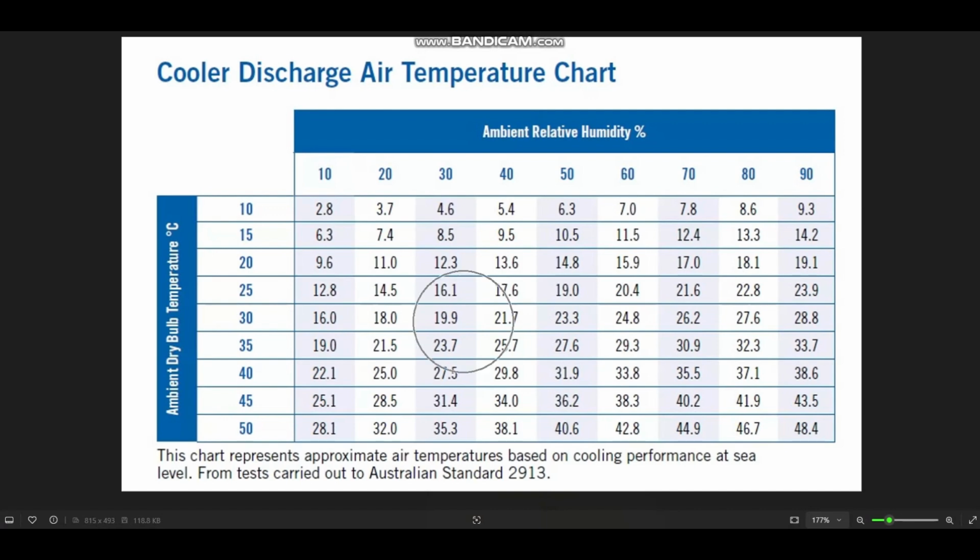So quick summary, 20 degrees at the bottom of your cooler, another 2 degrees through the flexible ducted network and all the twists and turns and the heat in the ceiling cavity, delivers the air at the ceiling at 22 degrees Celsius, picks up a bit more heat energy as it's pushing that heat energy out through the open doors and windows. It's 24 degrees Celsius.